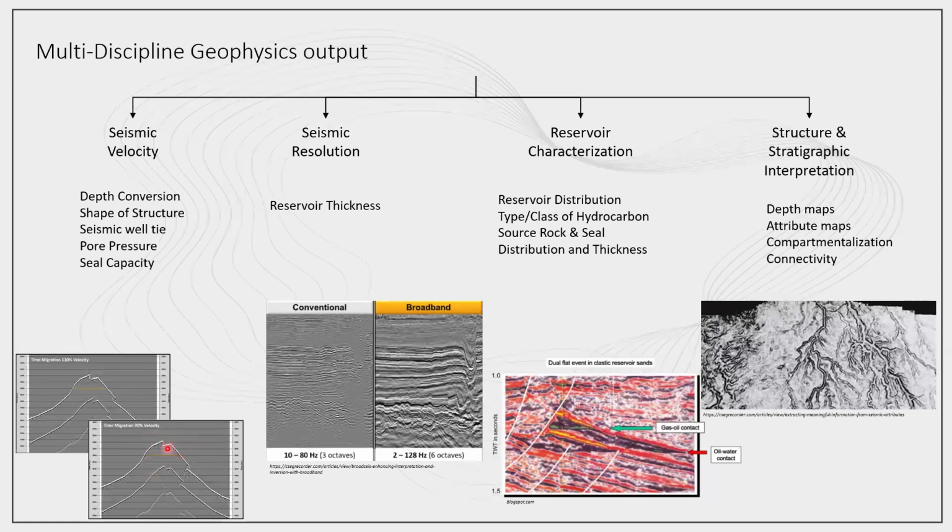And if the structure is steeper, how is that affecting the stability of the structure, or how will that affect the borehole stability because of the stresses coming from the structure? All of that we are calculating from the velocity. Velocity we can convert to pore pressure.